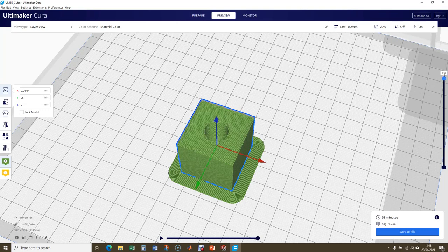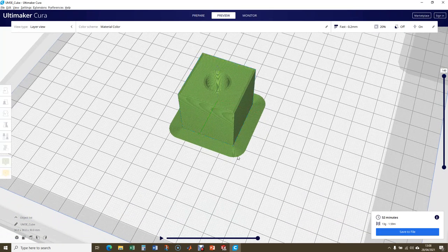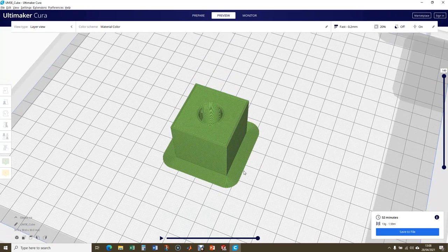Okay, so if we go up here, you see there's our solid layer, and we have 3 or 4 solid layers. The more we add, the better a finish we'll have on our top surface. If we only had one layer, you would have little gaps and imperfections, and it would probably be a bit bumpy, where the lines of material would sag between the triangles. So that's why we have those mesh, and that's a quick overview of a 3D printed part.